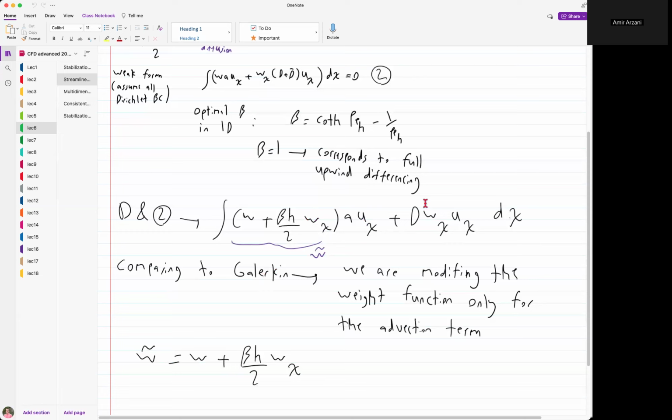If you get the second derivative and you're using only linear shape functions, the second derivative becomes 0. The second derivative of a linear function is 0. So that will just go away. So essentially, even if you define this in a consistent manner, meaning that you just change this W here to be W tilde, partial x of W tilde, if you are using linear finite elements, you're going to get the same thing. Essentially, you're still not consistent if you're doing linear finite elements.